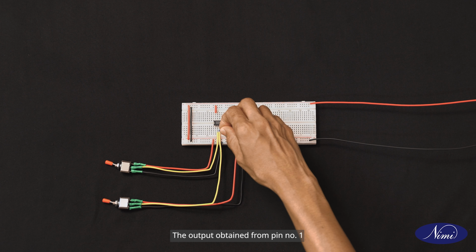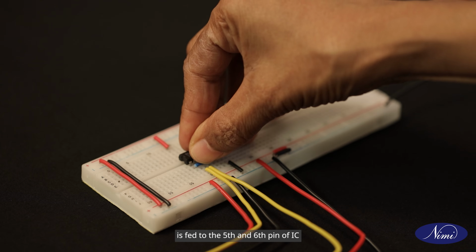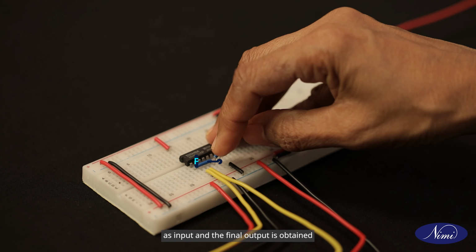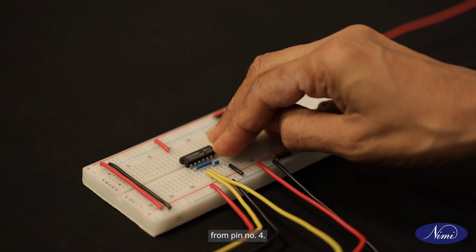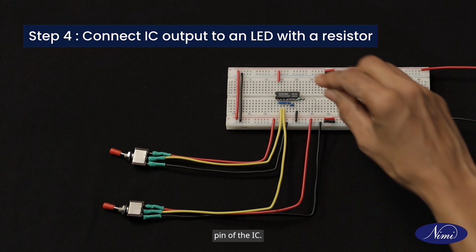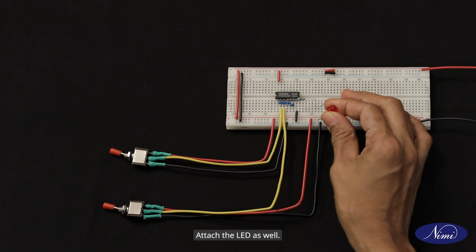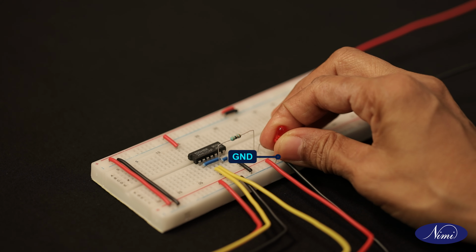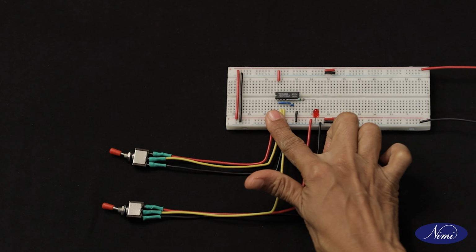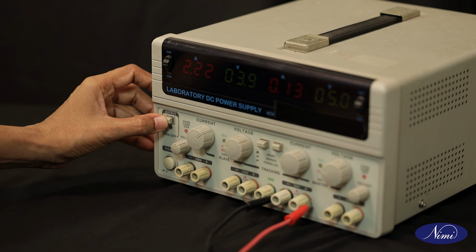The output obtained from pin number 1 is fed to the 5th and 6th pin of IC as input, and the final output is obtained from pin number 4. Connect a resistor to the output pin of the IC. Attach the LED as well. With everything checked, switch on the 5-volt DC supply.